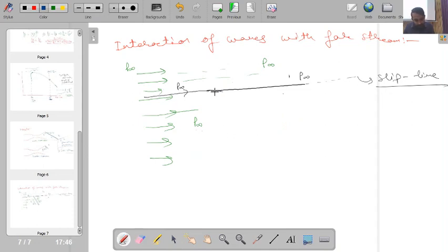So let's say our shock wave is like this. Okay, if the shock wave is like this, then the flow will deflect something like this. Fine. This is how the flow will deflect. So this is my point 1, this is my point 2, and here P2 is greater than P1, which is equal to P infinity. Now when this shock wave is touching this boundary, ultimately this pressure has to become equal to P infinity only, and only then can this straight slip line exist.